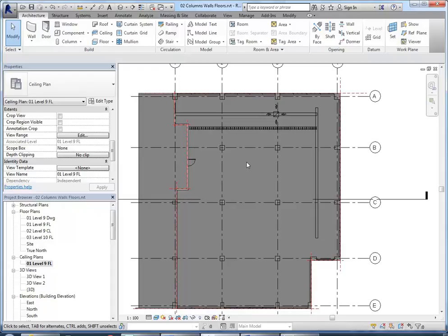You can be really creative with those, but they're fairly easy constructions to understand once you know how a suspended ceiling is built, because they're all just hanging from the floor structure above, and you can do virtually any shape you like. And again, you can model those things fairly easily in Revit and show them really clearly in your ceiling plans.